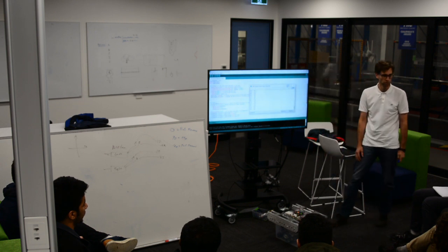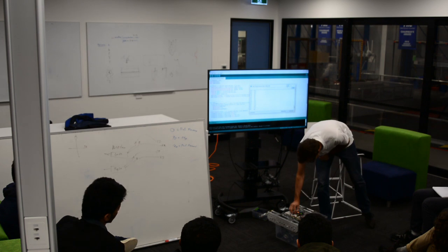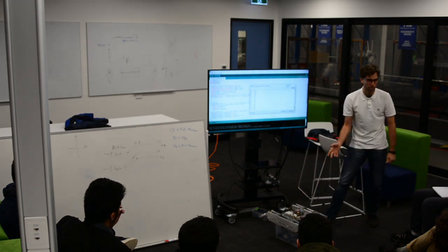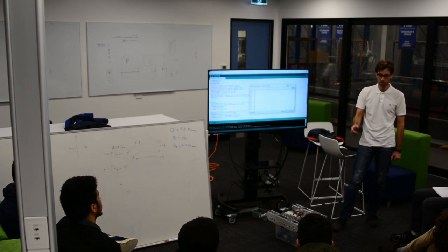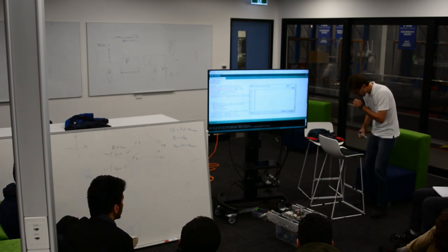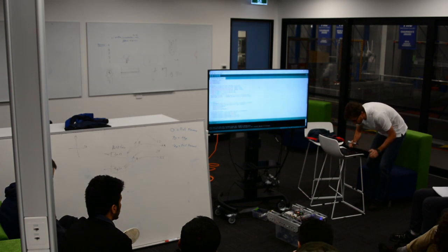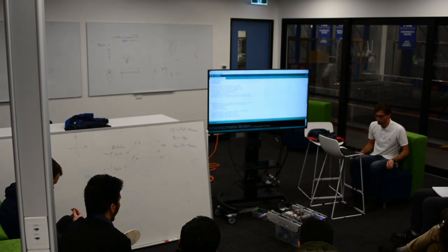It's not necessarily jumping by that much. Only 6 or 7 or 8, maybe 10 ticks. There's a 13 tick overshoot. More than we want, and it sounds awful, and it stresses things. It's going to vibrate things. Screws are going to fall out. We're going to drain our battery more because we're throwing lots of current into it all the time.